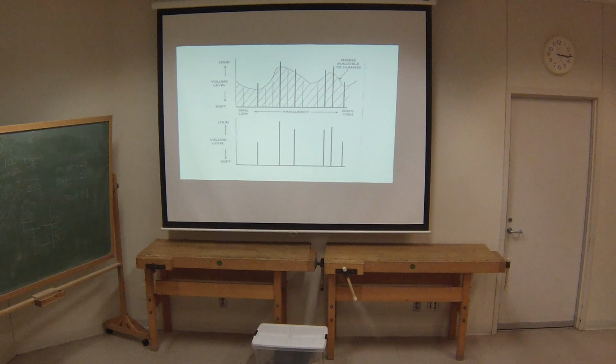It's done on the fly. So when you come out of your AD converter, you've got your signal in the digital domain. The first thing that you do is go from the time domain to the frequency domain. And once you're in the frequency domain, the signal is evaluated for its frequency components. And you're going to see that this is done on the fly. It requires very fast processing, even in the audio domain. But in the video domain, we do something very similar.